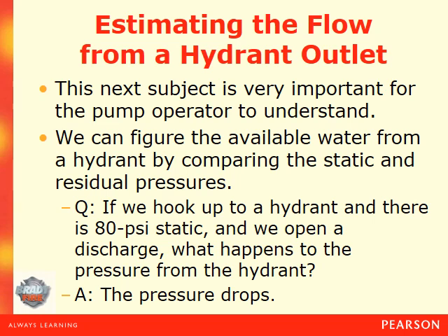The next subject is very important for the pump operator to understand. We configure the available water from a hydrant by comparing the static and the residual pressure. Static pressure, again, is the pressure on the hydrant when no water is flowing. Residual pressure is what's remaining after the hydrant is flowing.